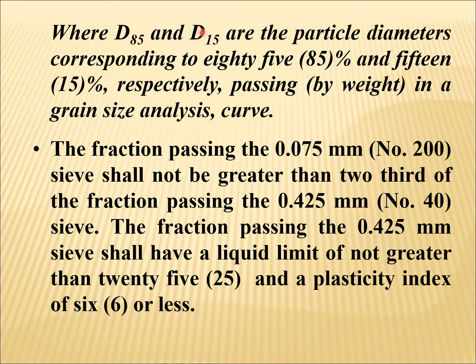The fraction passing the 0.075 millimeter, that is the opening size of the sieve number 200, shall not be greater than 2/3 of the fraction passing the 0.425 millimeter, that is number 40. The fraction passing the 0.425 millimeter sieve shall have a liquid limit of not greater than 25% and a plasticity index of 6 or less.